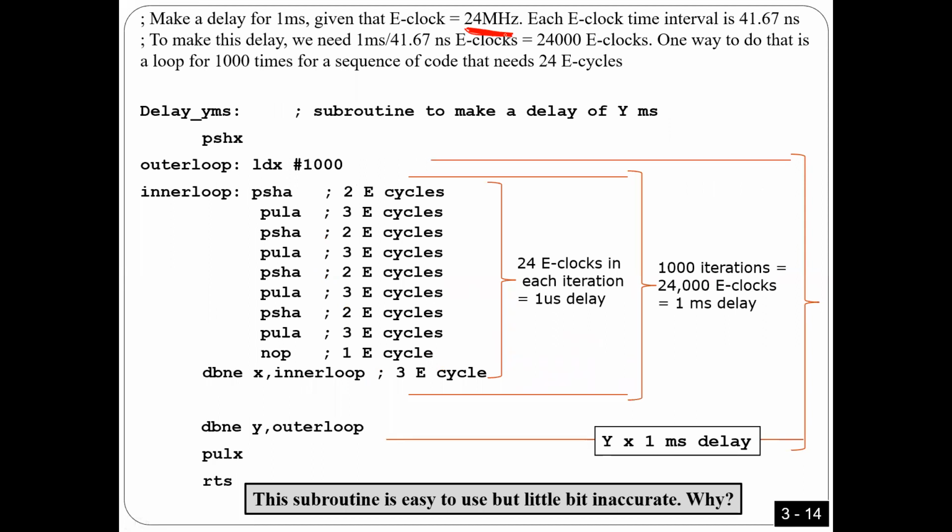So look at the idea. The idea is I'm going to execute instructions. As I explained before, every instruction takes some time, or consumes some time, to execute. So the idea here is I'm going to execute some instructions that are not doing anything functionally. I just want to waste the time, because I want to stay here for 1 second, or 100 milliseconds, whatever. So I want to waste some time.